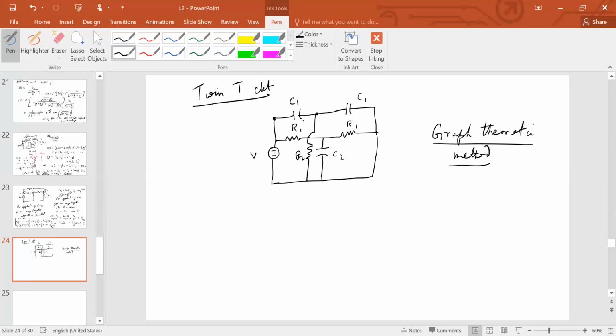So consider the two nodes corresponding to every element, okay? So these are all the same node, yeah? They're equipotential, okay? So how many such nodes can you find here? These are again the same node. Let's say I just name them in this fashion. I call this node 1. Both of these are node 1, okay? And I call this one node 2, this one node 3, and this one node 4, okay? And then call this the ground, so maybe call that node 0,